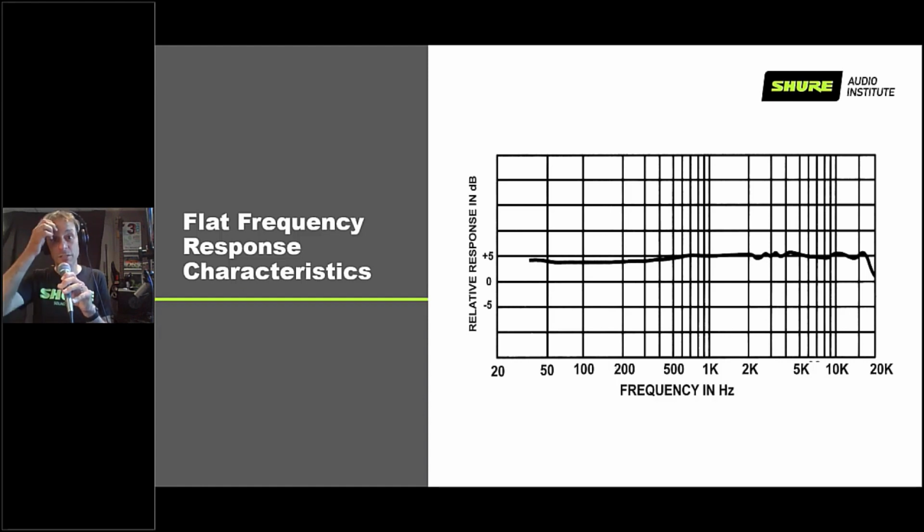The human voice doesn't generate much energy down there, and you just end up picking up a bunch of noise: stage noise, vibration, wind noise, P-pops, all that sort of thing is in that low frequency area. So if you are miking something that has significant low frequency content, that might muck things up.